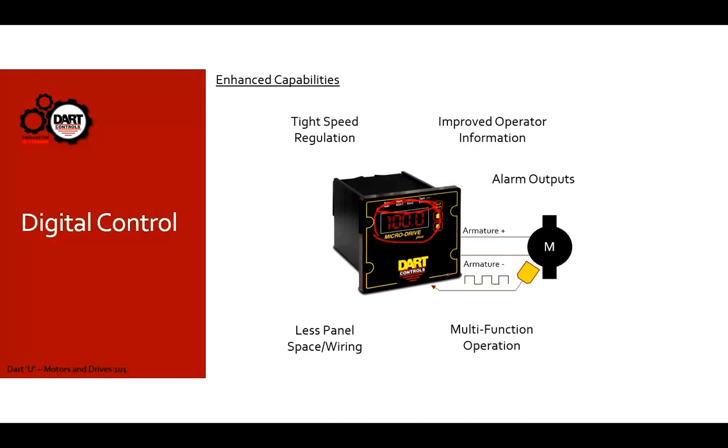We can actually have alarm outputs, like I mentioned, one or more alarm outputs based on the health of the control itself or what's going on in the application, in the operation itself. Is my actual motor speed outside of some sort of limit? Has my motor been running... like I mentioned before, if it's running full speed, I can alarm on loss of encoder input. So there's many things that we can do to avoid waste in the plant.